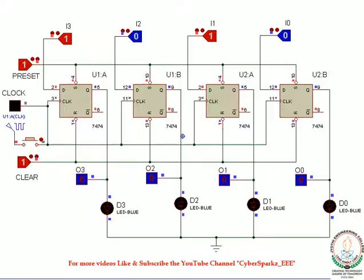Now set the input data to 1010 and a clock pulse is given, which will set the output of each of the flip-flops to the required value. So within one clock pulse the input data is stored into the flip-flops and we are obtaining the parallel output as the same input data, 1010.